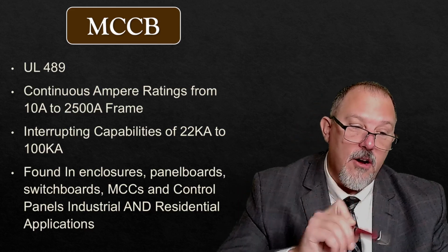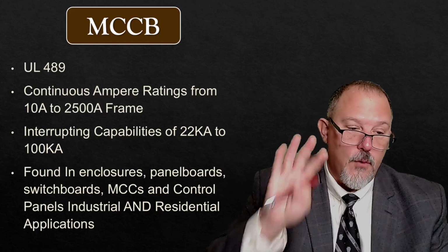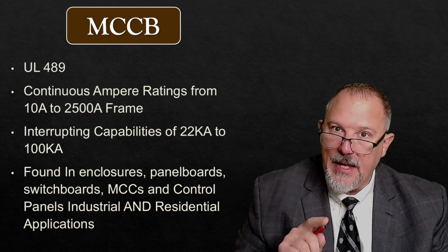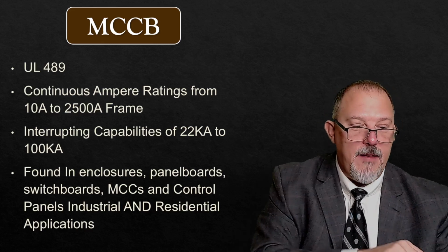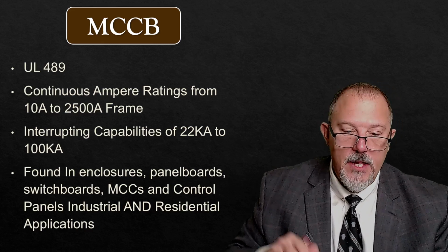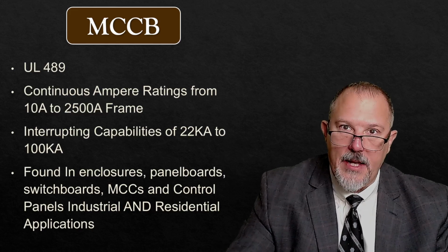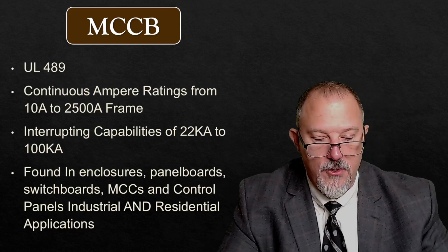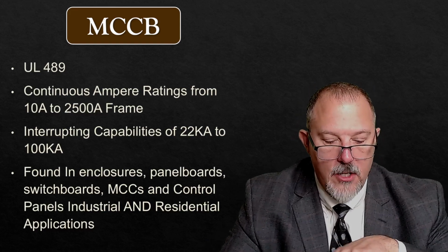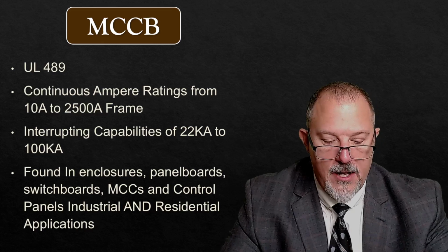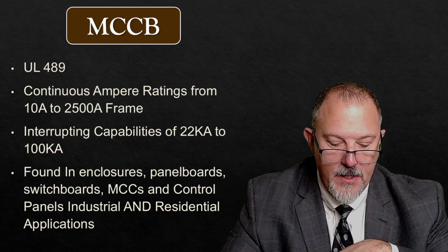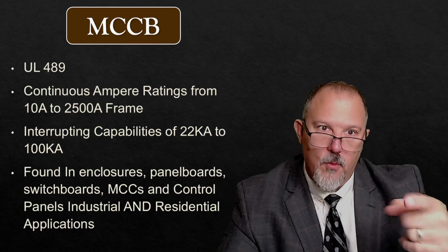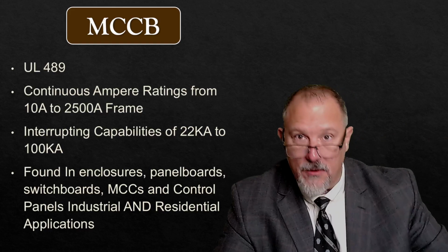And look at the arc flash PPE categories for those 4 areas. The first one for 240 volts and below is a PPE category 1, which tells me I'm in a 4-cal outfit. The other 3 are PPE category 2, which tells me I'm in an 8-calorie outfit. Everything else, which would include a 20-cycle clearing time, a 30-cycle clearing time, a 15-cycle clearing time, are not molded case circuit breakers. They are something else, and you've got to look down at the table, and we're going to talk about those, insulated case and power circuit breakers, later.